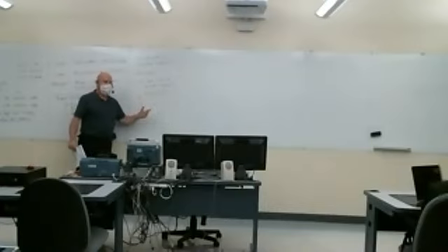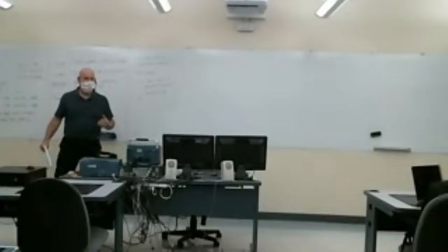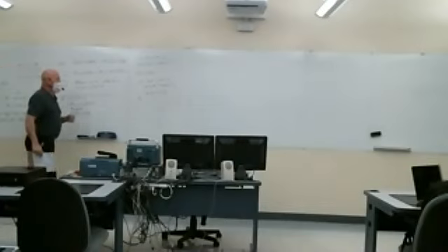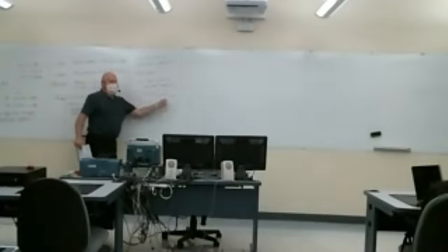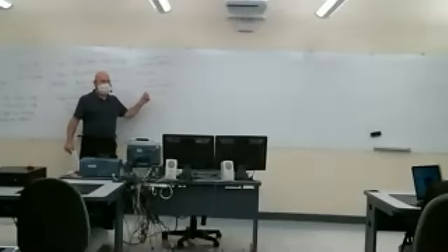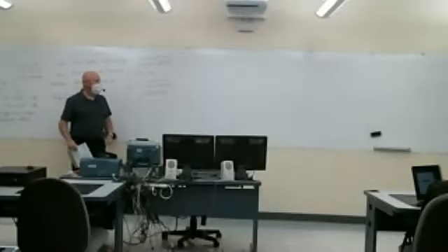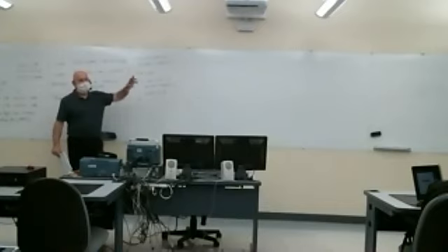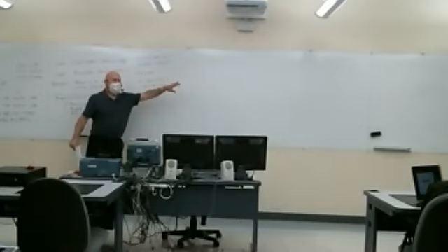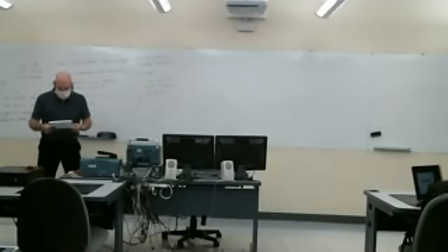This is one way to write an infinite loop, while(1). You could also do it with a for statement. And then this is just an empty body. Just do this forever. So this is all the microcontroller would do. In multitasking operating systems, you typically want to avoid infinite loops like this, so that if you've got other tasks running, instead of this task tying up processor time, you'd run other tasks.